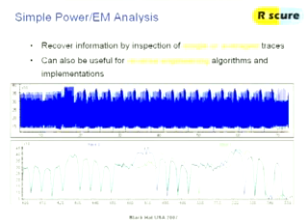Actually, this was a lookup table in a crypto algorithm where the table is 512 bytes. And this is an 8-bit processor. So it needs to look up this index, but it only has 8 bits. So that 9th bit has been made into a decision whether to go for the left table or the right table, or the upper or the lower, or whatever. And that manifests itself as a time difference that you can see when you measure.